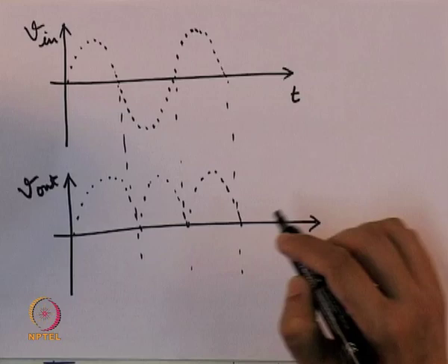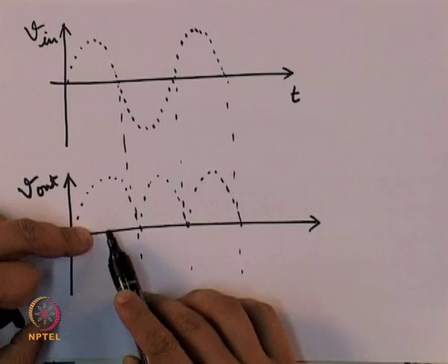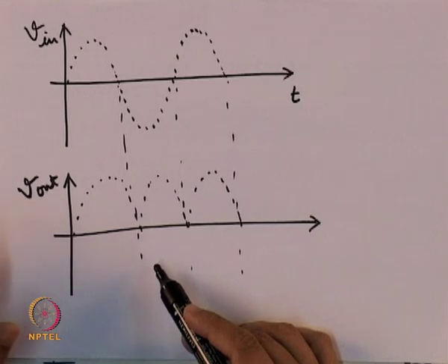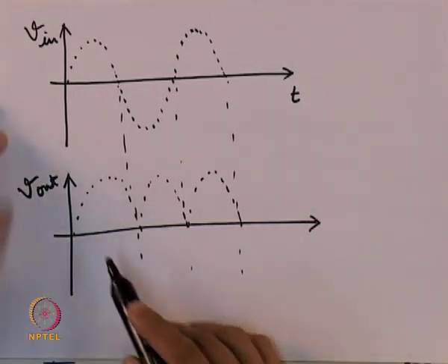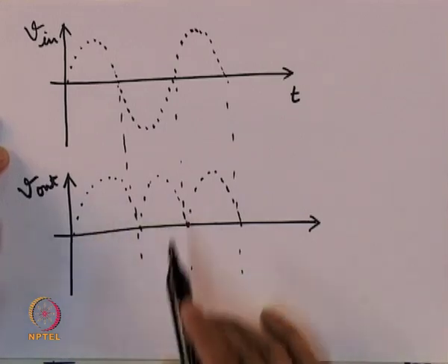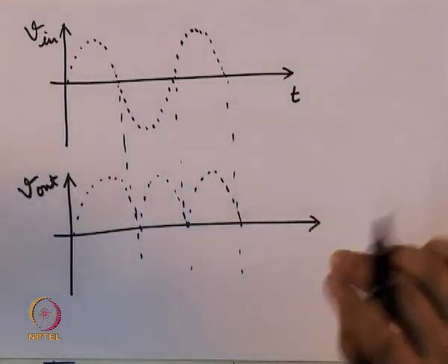This is also a form of rectification because now all the voltages at the output have no negative component, they have only positive components, and so though not equal to the ideal, they do approximate DC. Of course, a DC voltage which varies slightly with time. This is the principle on which we are going to design our rectifier circuit.